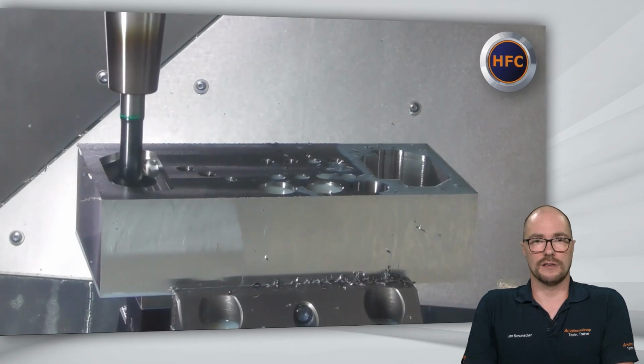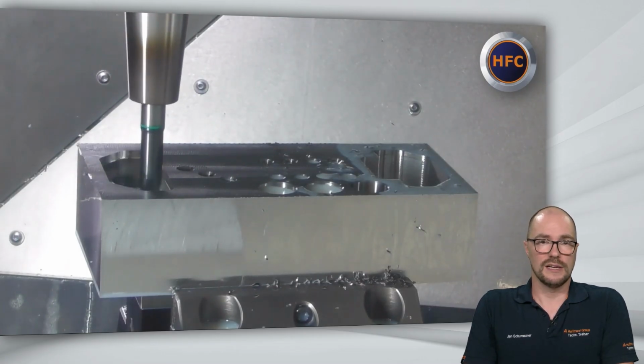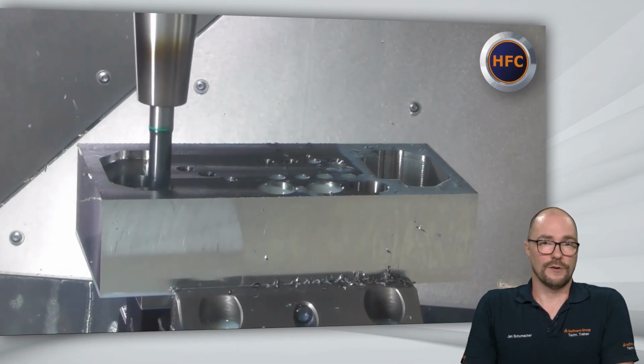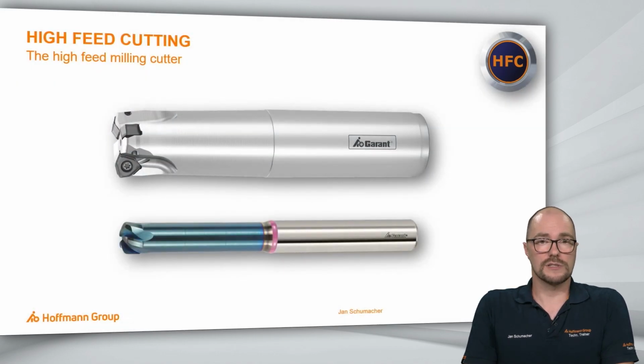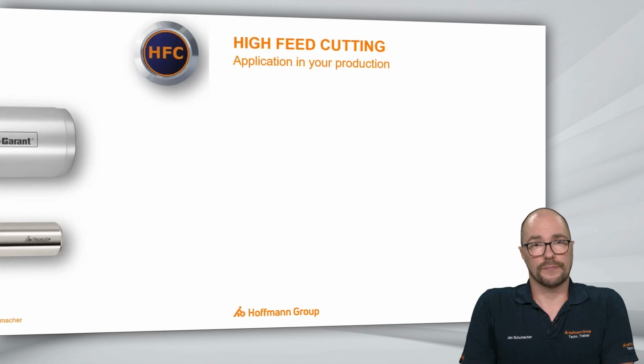It depends on the workpiece material. It depends on the overhang of the tool. So here you can see the tools, and only the very left part of those tools is used, only the top part. We don't have any real cutting edges on the side, on the circumference, so only the top is to be used.